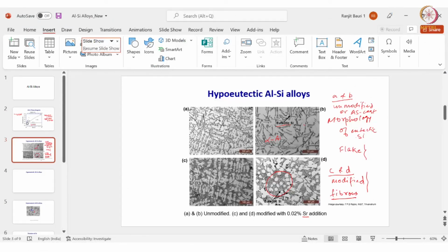That decimal point can either be 0 or 1. 0 indicates it's a casting, and if it is 0.1, that would indicate that it is an ingot. So it tells you the product form, either the casting form of the product shape that you need, or the form of an ingot.